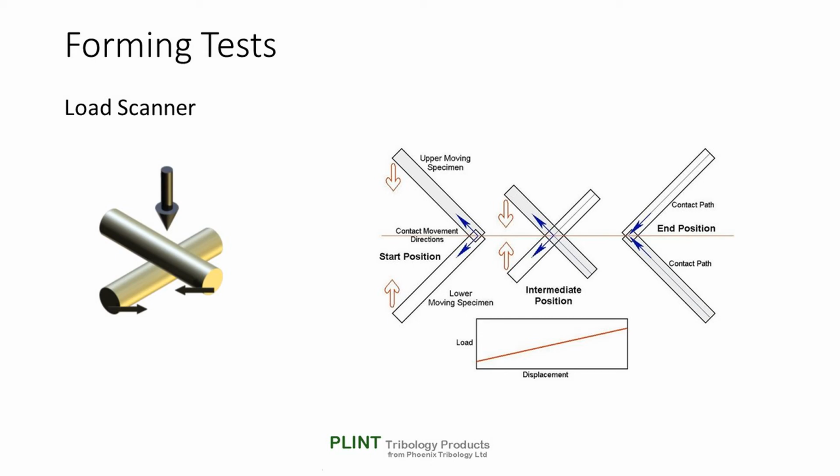The contact spot is the area over which the contact load is distributed. The load is applied by means of a pulley mechanism and spring arrangement connected between the load arm and the lower specimen carriage. The loading arrangement is such that the load increases or decreases with relative motion of the specimens, thus resulting in a unique load at each unique contact point on the two specimens.